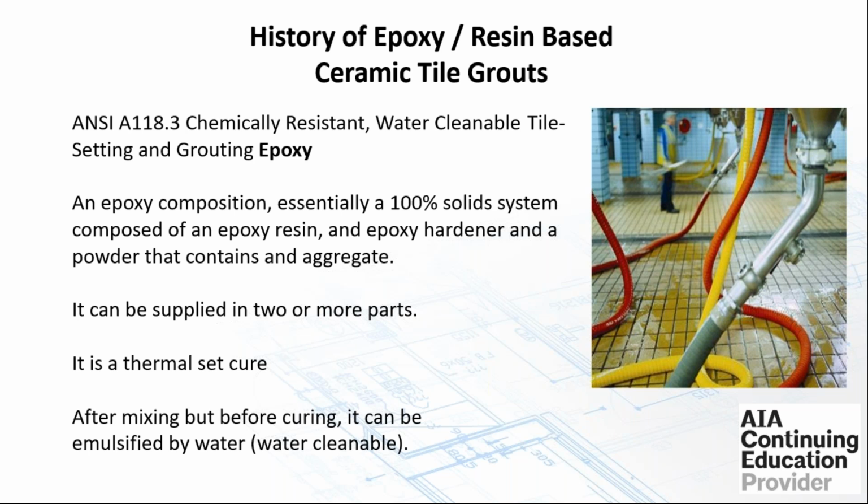I had a really interesting learning experience many years ago where we weren't paying attention and didn't cover the drains properly at a winery. The epoxy wash-off water went down the drain and it all hardened, and it cost us to come in and tear up the drains because they got plugged from the epoxy water solidifying in them. So there was a lot more involved with working with these types of products, and they were more difficult to work with. We've seen a lot of changes with epoxy grouts over the last number of years, to where they're a lot easier to work with, even being 100% solids epoxy.